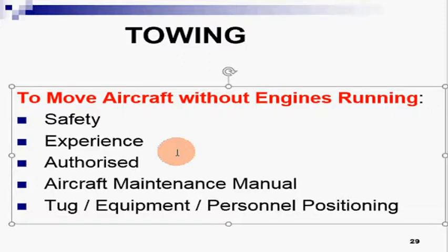Dear students, it is often necessary to move an aircraft without starting the engine, for example, to position it for servicing or to enable passengers or cargo to be loaded. If this operation is not carried out properly, severe damage can be caused to the aircraft. If it is necessary to use untrained or inexperienced persons to help move the aircraft, the person taking charge should instruct them thoroughly before starting, so that they fully appreciate what they are required to do.